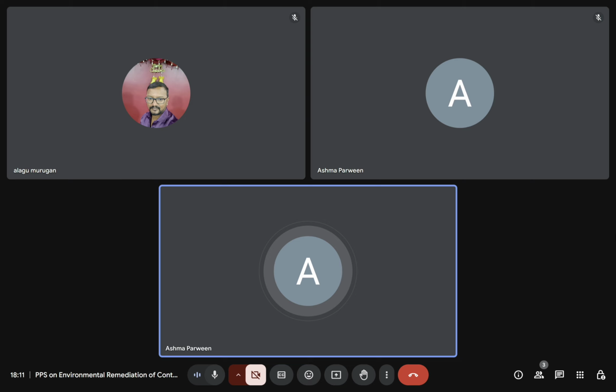For this we found the retardation factor, which further increases when there is some NAPL in the sediments. Based on these, we saw that the pump and treat method is not efficient where the contaminant is sorbed on the soil or sediments and is in equilibrium with water, and also when there is some NAPL, that is non-aqueous phase liquid, present in the pores.